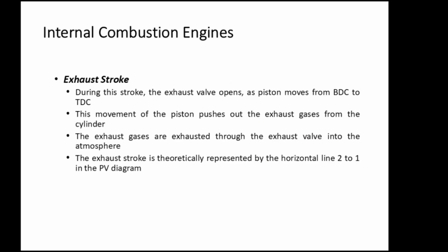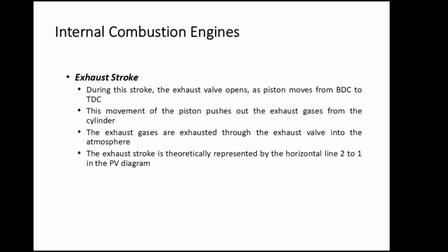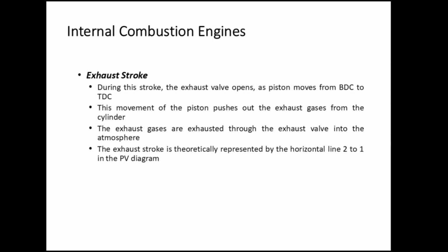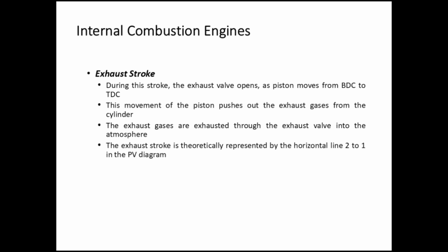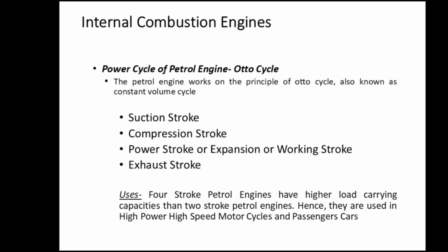Internal combustion engines. Exhaust stroke. During this stroke, the exhaust valve opens as the piston moves from BDC to TDC. This movement of the piston pushes out the exhaust gases from the cylinder. The exhaust gases are exhausted through the exhaust valve into the atmosphere. The exhaust stroke is theoretically represented by the horizontal line 2 to 1 in the PV diagram.